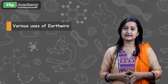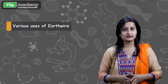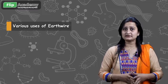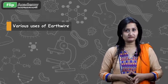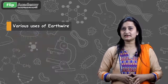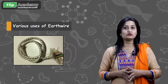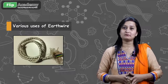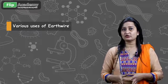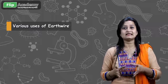So how do these accidents occur? Let's see the probability. If you are going to use the electric iron for a long time, or in some condition due to overload of current, the insulation of the wire melts. Then the wire of the electric iron gets worn out or broken at some particular point. So when the insulation gets broken or worn out, the wire gets naked.